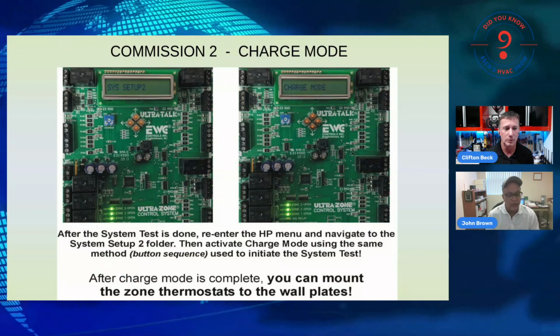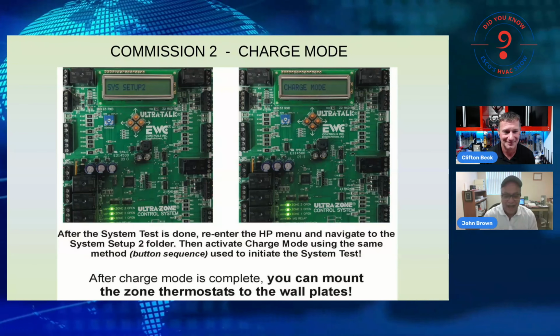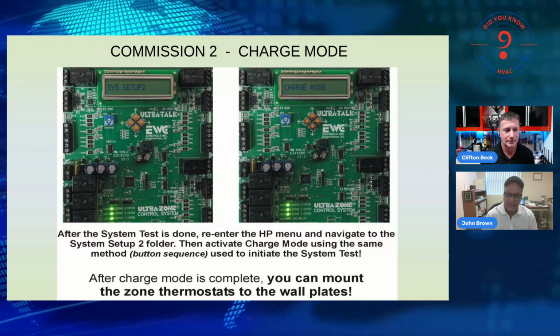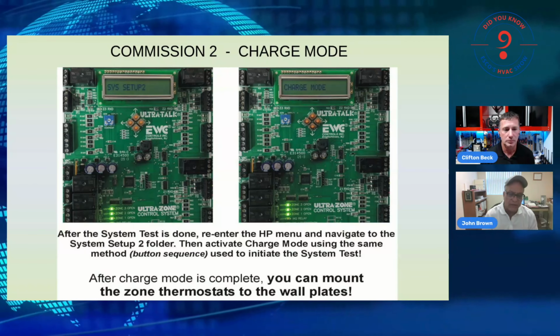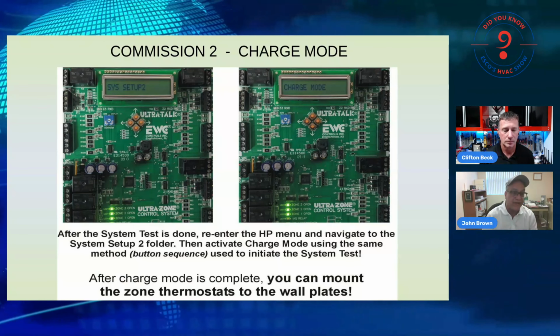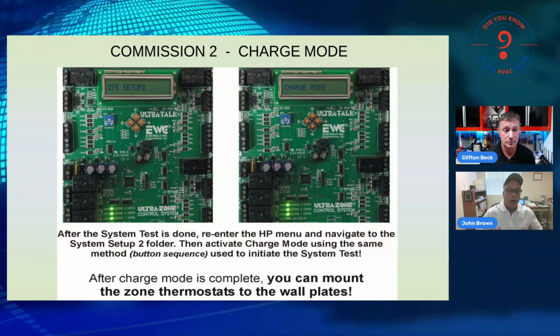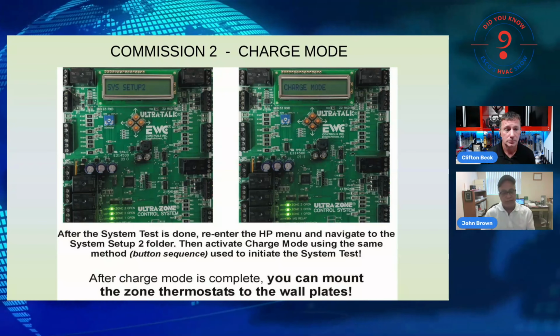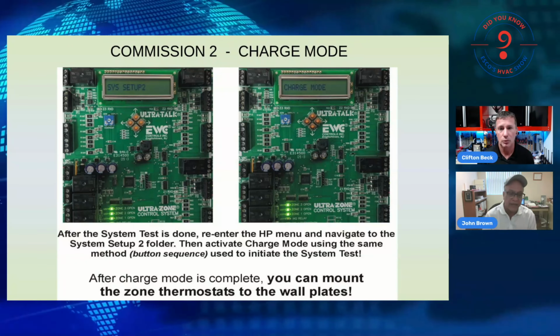Yes, you will. Once the power comes back on, I imagine this does happen, and that's an excellent question. If in the mind of the outdoor unit, the system test was incomplete, it did not get to finish, the E11 is not going to go away. So once you restore power, you're simply going to have to start the process all over again and achieve a successful system test.